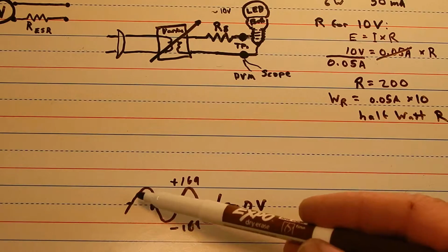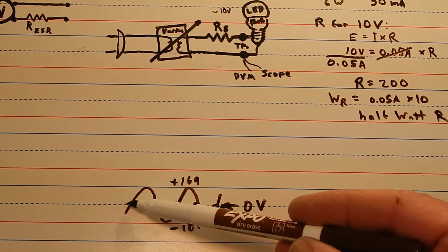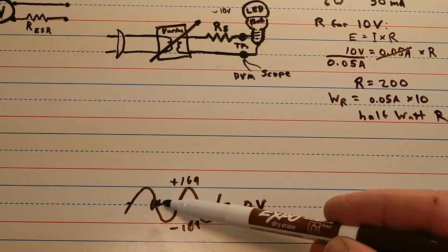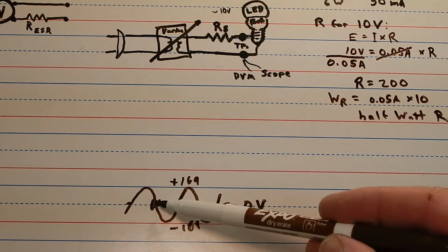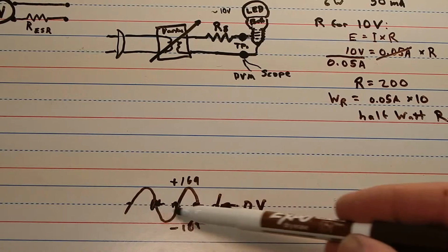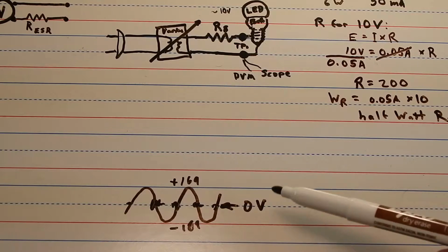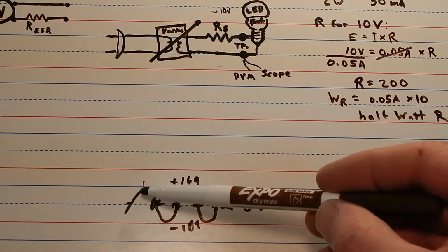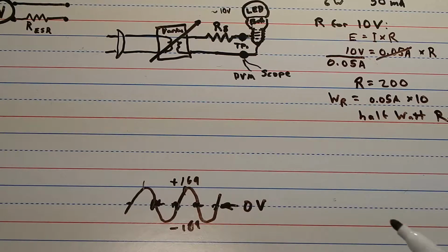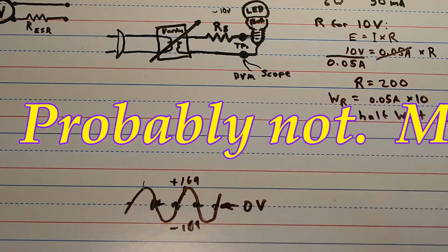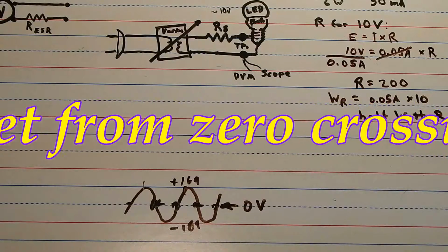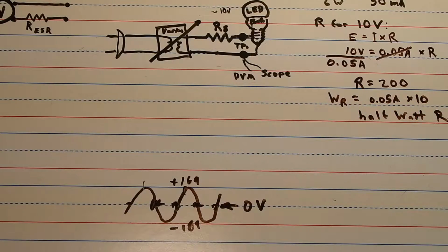Well, the X10 has a zero crossing detector, and that's when it launches its data. When it sees a zero crossing, it launches its data. And I guess when they designed it, they figured that'd be the cleanest part of the wave. In retrospect, to make it more compatible with today, it would have been nice if they had made it at the crests. It probably would have survived better than it does at the zero crossing. I guess the thought is, at the peak, with a motor or anything else, you're transferring a lot of power, so the impedance might be lower at that part of the wave, who knows.